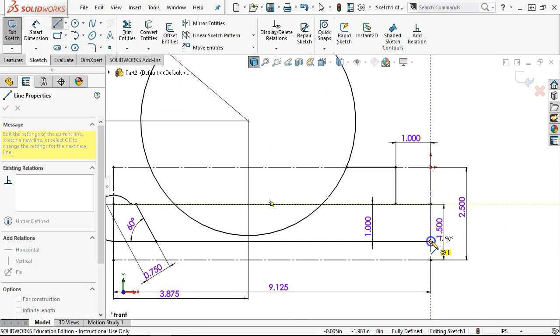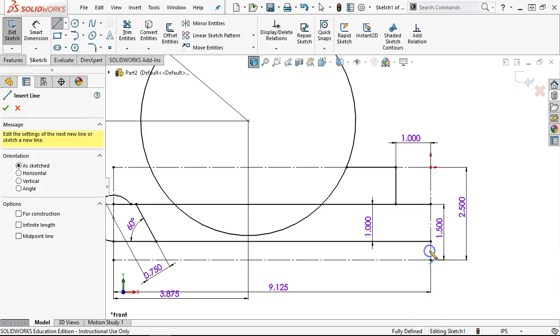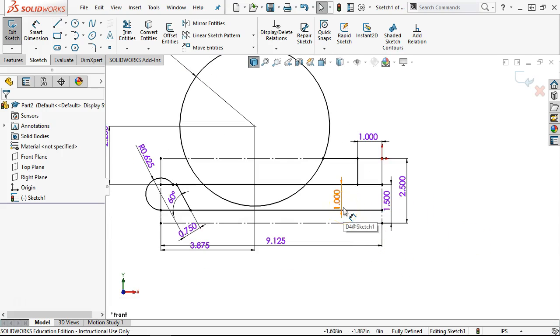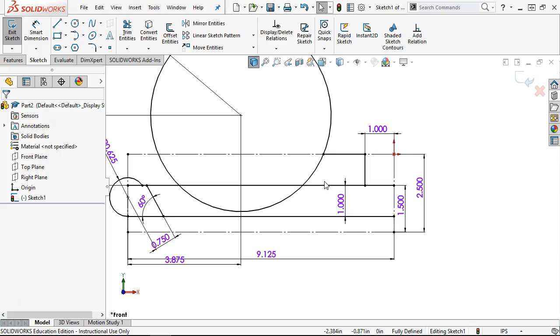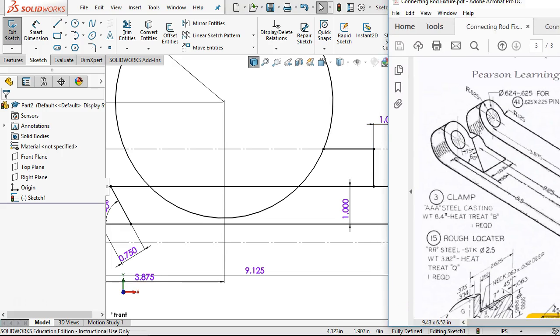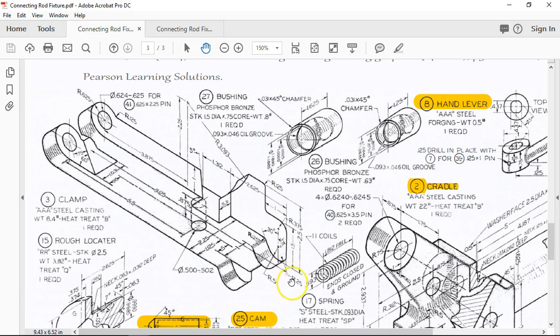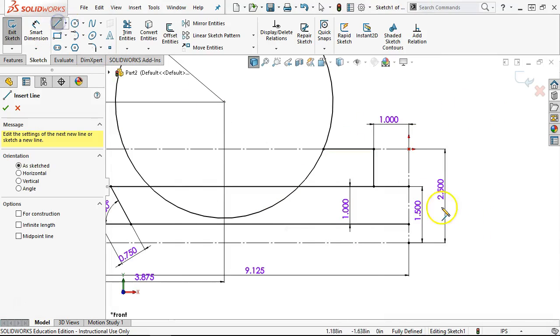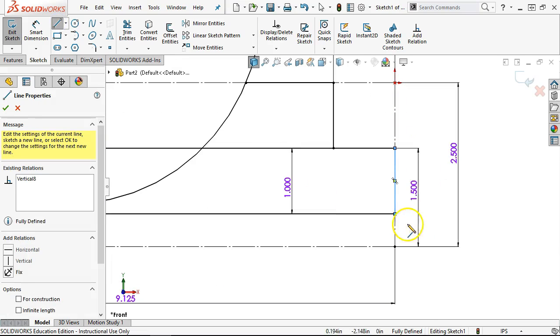Okay, got a little button happy on that one. And then a radius of 0.25 going into a radius of 0.5, another one of those interesting ones. Yeah, that's what it says, 0.25, and then it picks up and goes to a radius of 0.5. And 30 degrees, picking it up off of the line. So I'll go ahead and put that segment in.